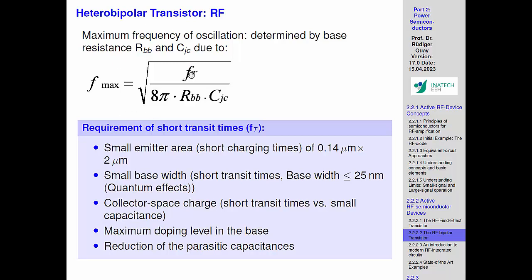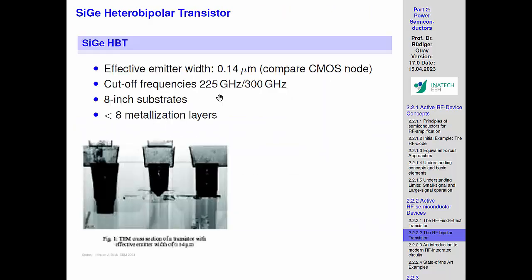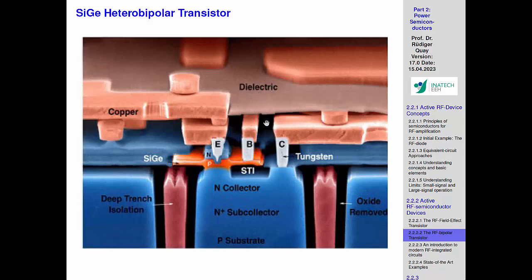So if you have a relatively high current gain cutoff frequency, how do you get a very nice power gain cutoff frequency? It's simple. Of course, a high current amplification is good. And then you have two additional parameters, which are not fully surprising. There is essentially the feedback capacitance. So this is this capacitance created here.